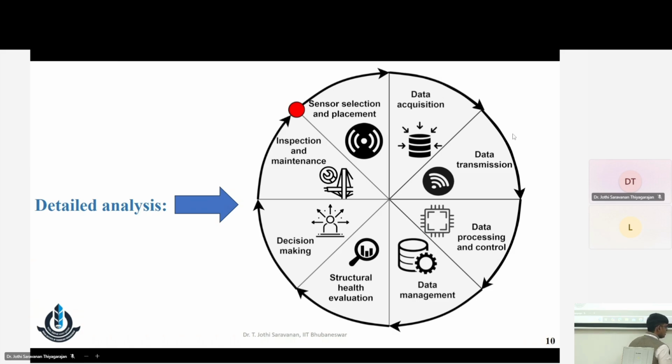Now let us say this is the first mode and this is the second mode. Let me draw again. Tell me where I should place the sensor to get the first mode. Any idea? At midspan? Sure. I am going to place a sensor at midspan, so you are going to get the first mode.